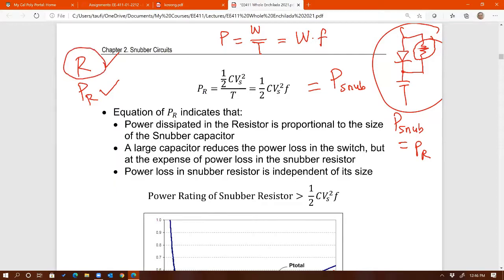Now, what is the significance of the R value in terms of sizing the resistance? What effect is directly related to the R value of the snubber resistor? Anybody? You know how quickly that cap gets recharged, right? That's correct. Very good. Or discharge, sorry, yeah. So the R value in ohms is important because it directly affects how fast the snubber capacitor discharges through the switch when the switch is turning off. So that's why it's important.